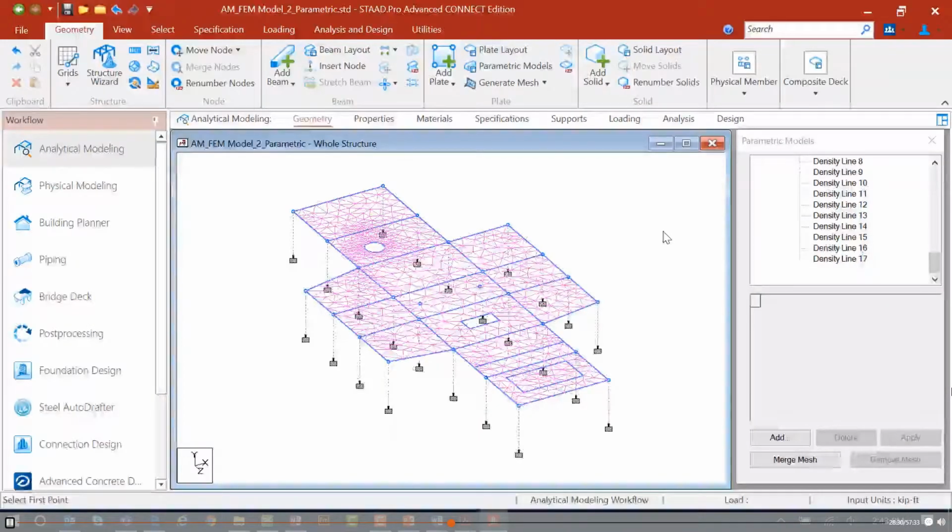Control points might be panel points of a truss, which supports a multi-span slab, or a foundation slab that supports several columns. And finally, your last advantage is to be able to control your finite element mesh with density lines, density points, and regions. So it allows for the definition of lines, points, and regions on the surface and control where nodes will be located within your finite element mesh. Again, after creating your finite element mesh in a prototype model, you can adjust the mesh density and preview all that information before committing it to the full system.